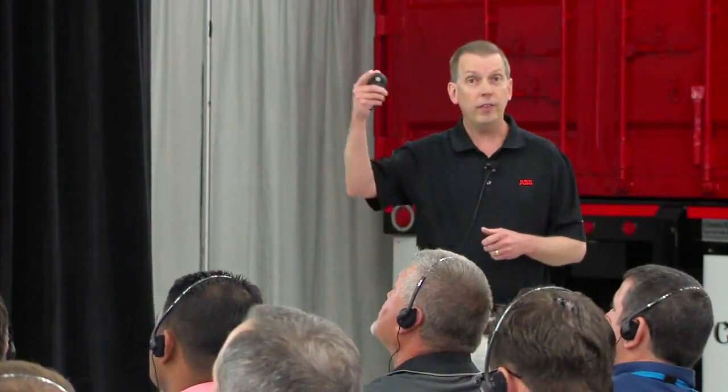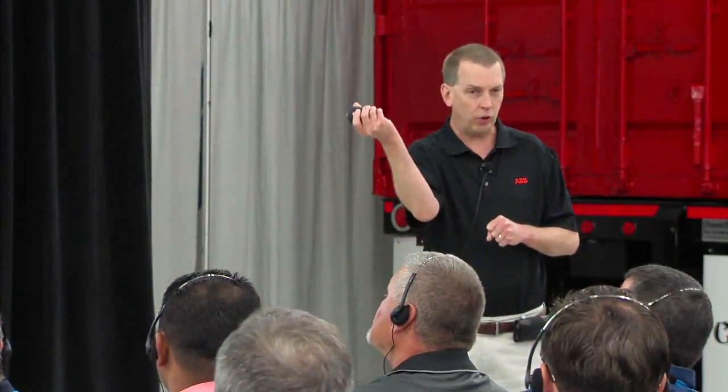You can take 50 over 1800, get a percentage number, and put that percentage number into this parameter, and then the drive will always run that percent extra on the frequency, so that when you say I want to run 900, you really get something pretty close to 900. You don't get 800. Okay? So it's a slip compensation.